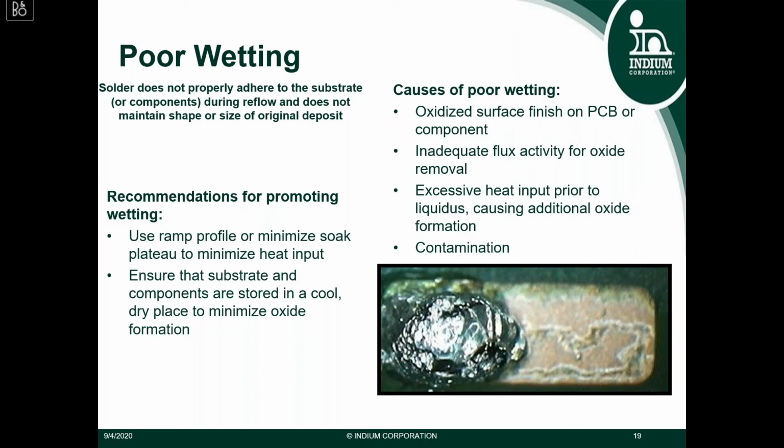Some ways that you could use the reflow step to promote wetting is to use a ramp profile, a straight ramp to peak profile, or minimize the soak zone in the profile to minimize the overall heat input to the assembly. Also, ensure that the components are stored in a cool, dry place that minimizes oxide formation, because as the components and the board go through the reflow step, oxidation will be more difficult to remove if it has a higher initial oxidation rate.